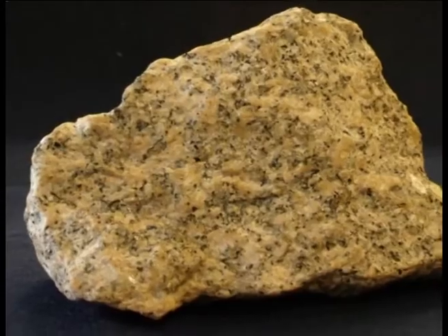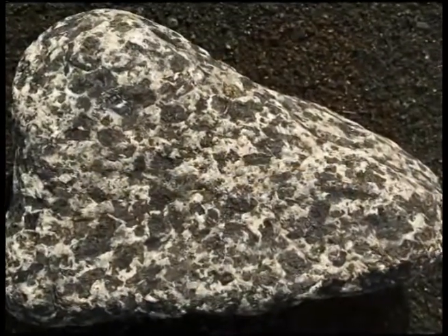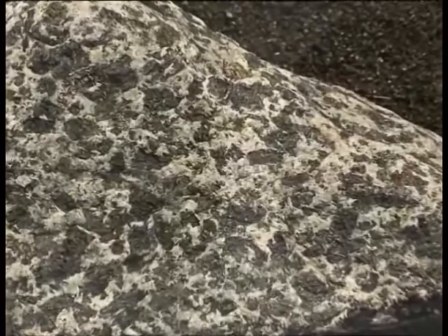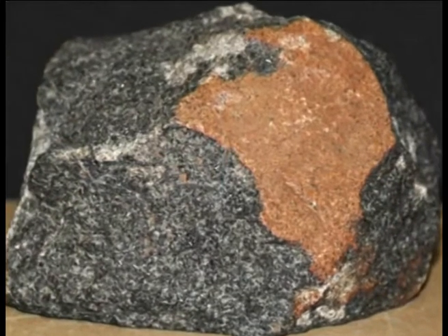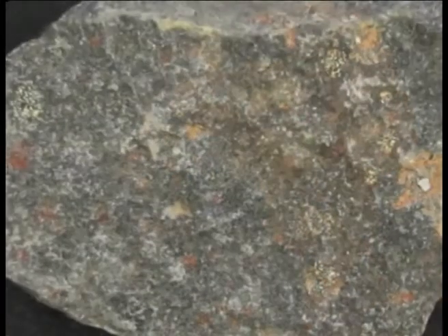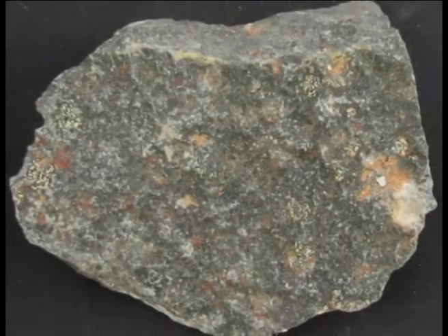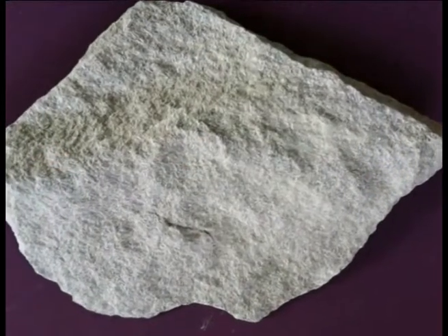Porosity. Porosity is an important engineering property in the sense that it accounts for the fluid absorption value of the stones in most cases, and also that a higher porosity signifies a lesser density, which generally means a lesser compressive strength. The shape, size and nature of the packing of the grains of a rock give rise to the property of porosity or development of pore spaces within a rock. Numerically, it is expressed as the ratio between the total volume of pore spaces and the total volume of the rock sample. Porosity is commonly given in percentage terms.